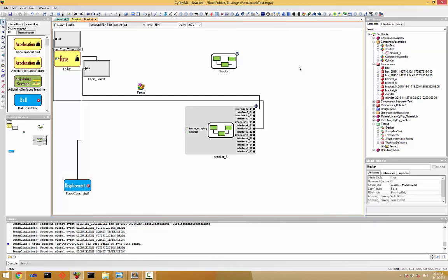While the interfaces are defined with coordinates dependent on the component geometry, different component geometries may be considered under the same testing scenario so long as they also contain similar interfaces. So while the location of the interfaces may change among geometries, if the interfaces exist, the loads and constraints may be applied programmatically without concern of the actual model geometry.